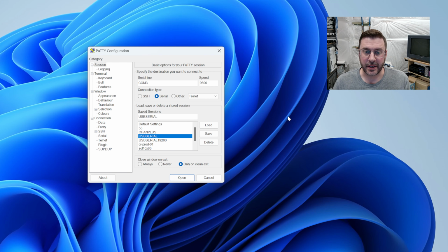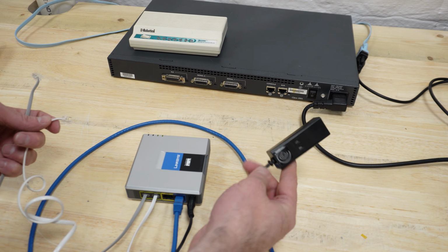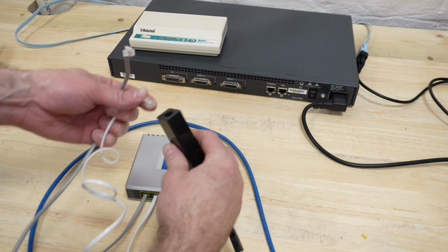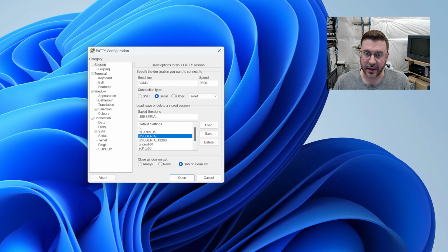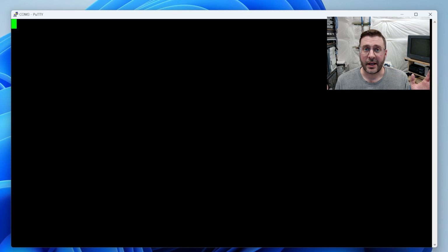And our good friend Putty is back. Remember that USB modem I was showing you? It's plugged into this computer, and we're going to connect to it at 9600 baud for consistency. Open up a terminal here. I am actually talking directly to that USB modem here, and I can do something called AT, and the modem has responded back and said, okay, I understand that, which is good. I will talk about this AT command set in more detail in a moment, but we can say ATDT, dial tone.